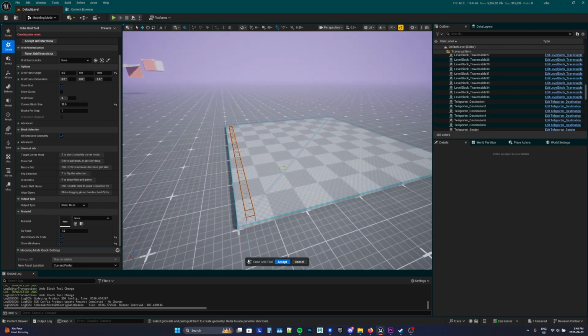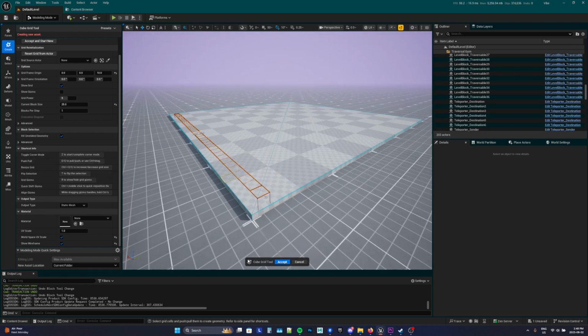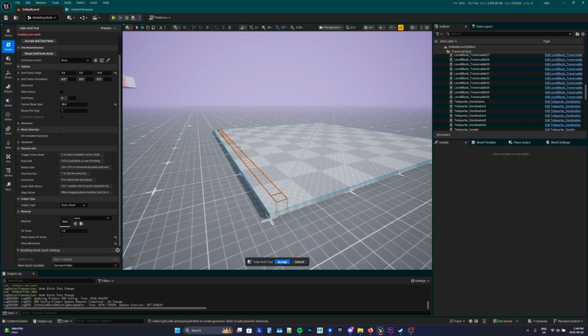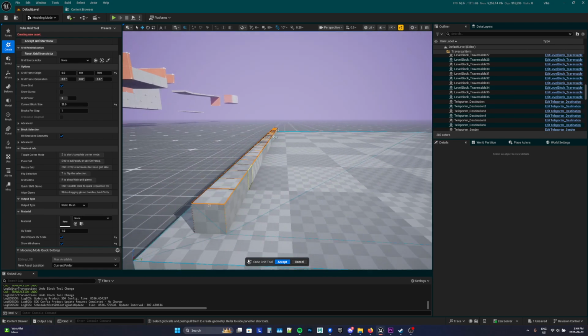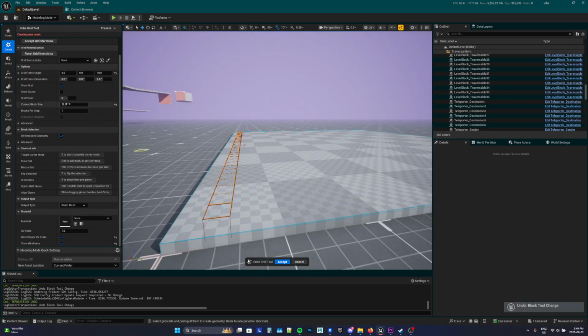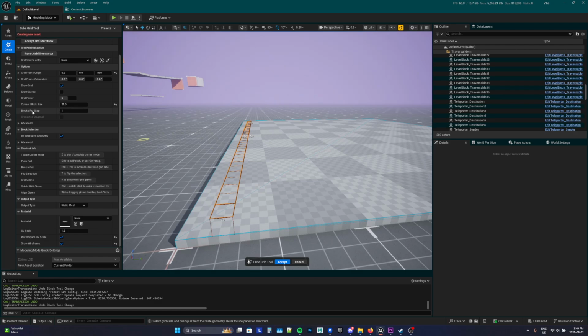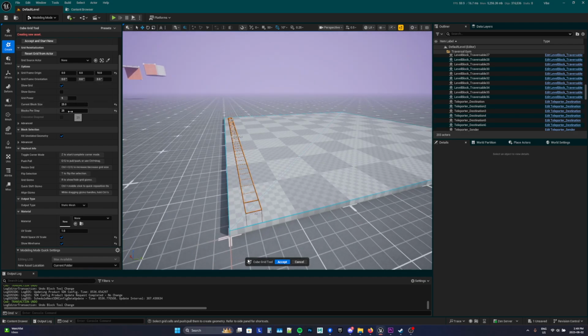And this is important because it will add complexity to your objects if you leave your block step at one for things like this. So if I go up, it's only going to go one block size up. And I don't want to change my grid's block size because then it's going to change the thickness of my wall too. So I want to change how many times per step this is going to go up when I push or pull.